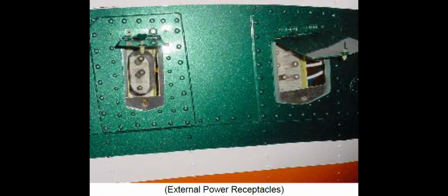The receptacle contains 3 pins for power connection and 2 additional pins that are jumpered, forming an interlock when the auxiliary power unit is connected. Jumpered pins complete a path for control relay activation and lighting of the caution advisory panel, X power connected advisory light.